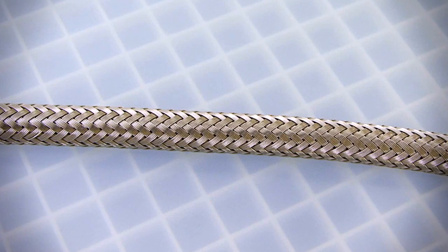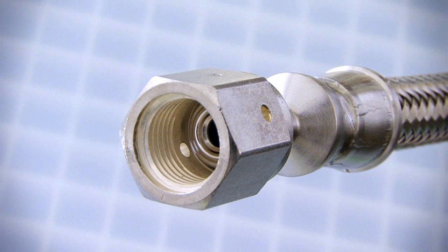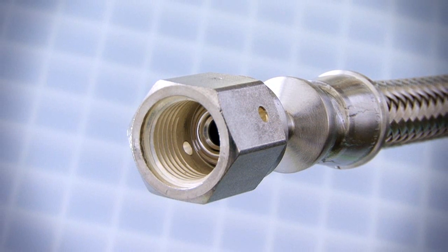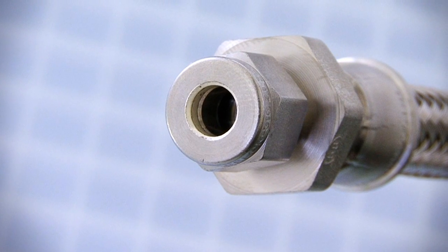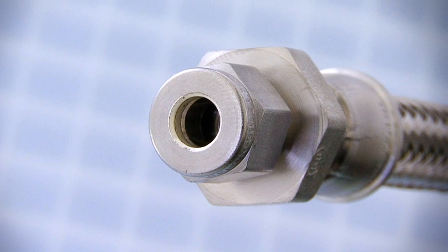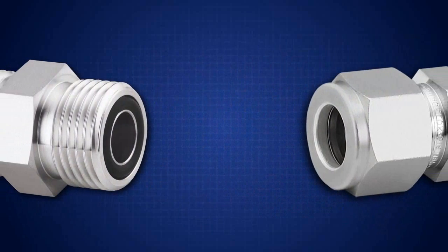After identifying the sealing method of the system end connection, a 1/4 inch VCR metal gasket face seal is selected for the first end. After determining the tube fitting is fractional and not metric, a 1/4 inch Swagelok tube fitting is selected for the other end. Note that it is important to identify the sealing method of the mating end connection and whether a connection is fractional or metric to prevent system leakage and unusable end product.